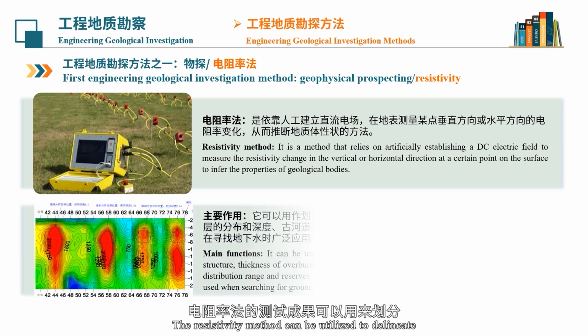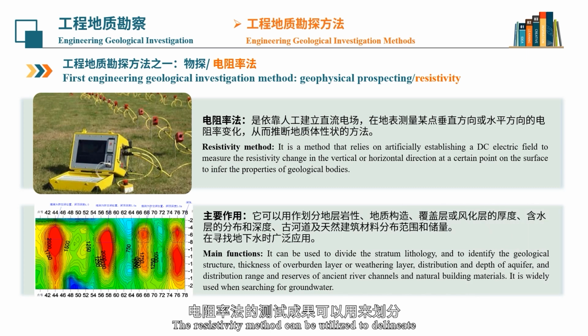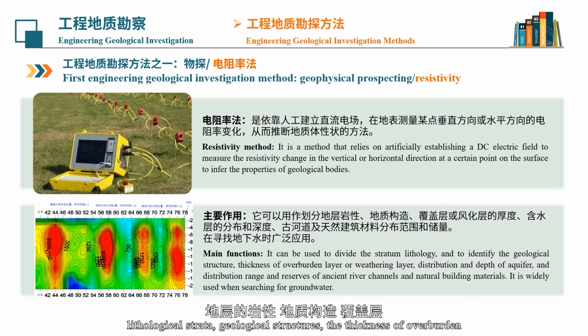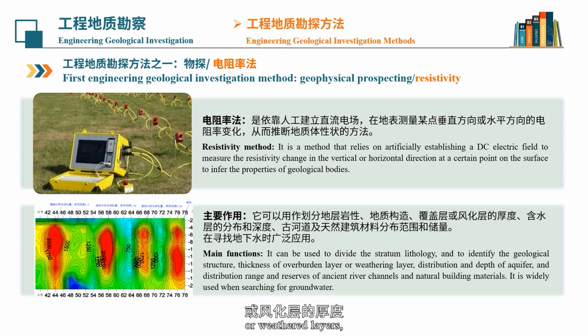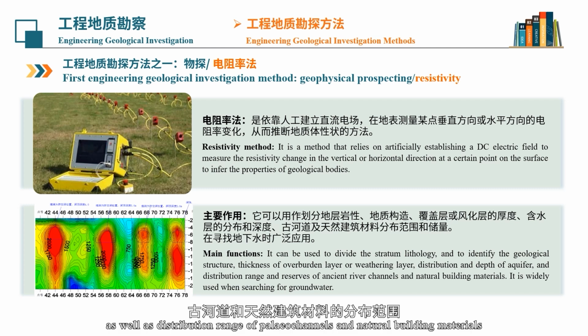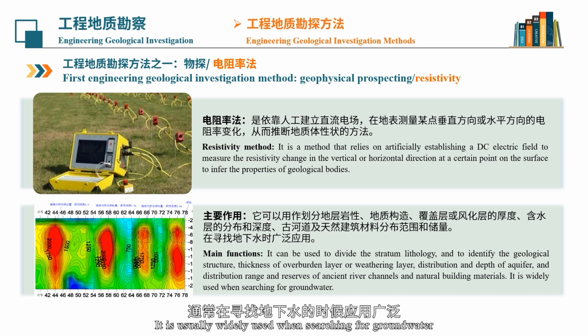The resistivity method can be utilized to delineate lithological strata, geological structures, the thickness of overburden or weathered layers, the distribution and depth of aquifers, as well as the distribution range of paleochannels and natural building materials. It is usually widely used when searching for groundwater.